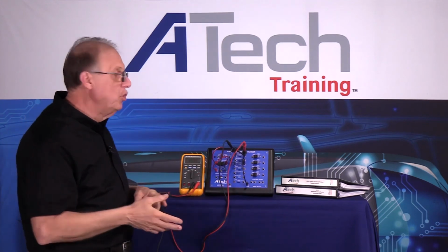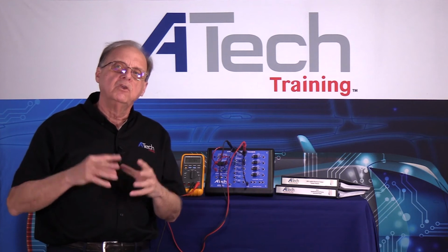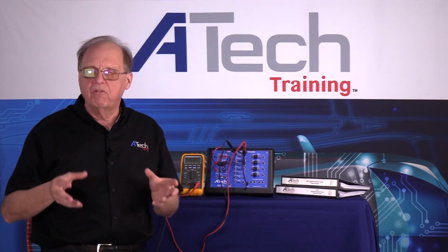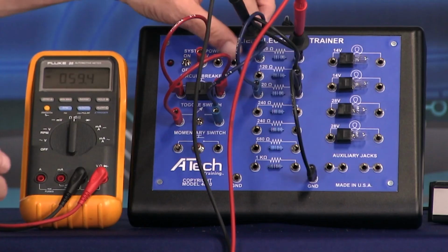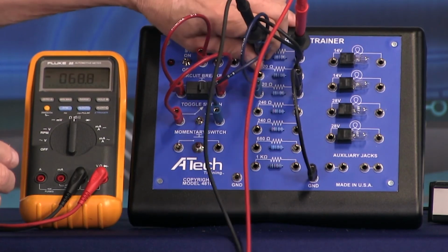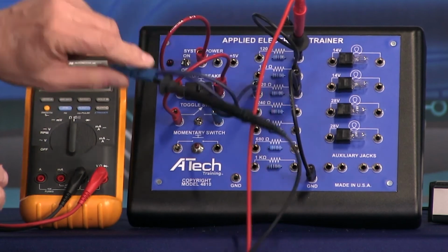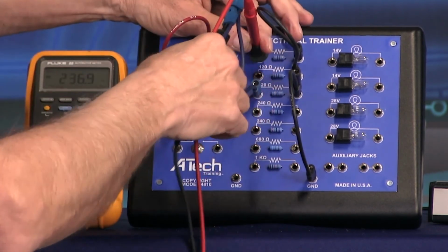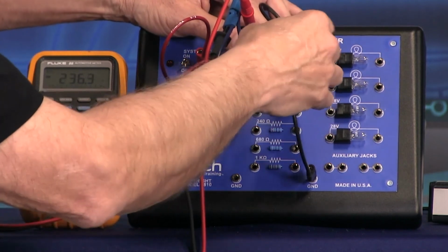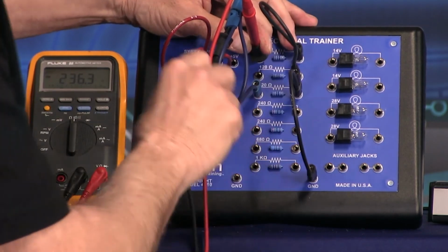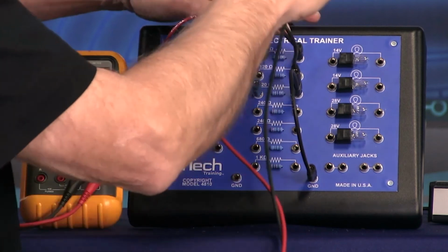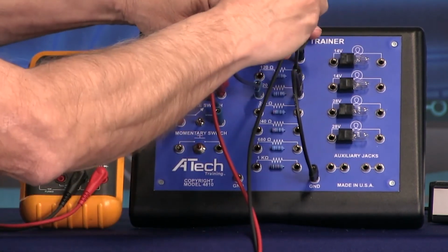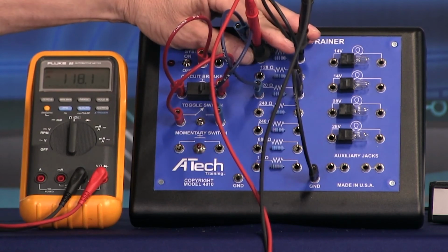Now, if you're using your ohm meter, you must teach, and emphasize this a lot, that you have to disconnect part of the circuit. So I'm just going to take this one out and watch what happens. Take my red lead, and I'm taking my red lead on it, and I'm going to find my black lead again, which is over there. And if I have my red lead right here, I have 118 ohms.